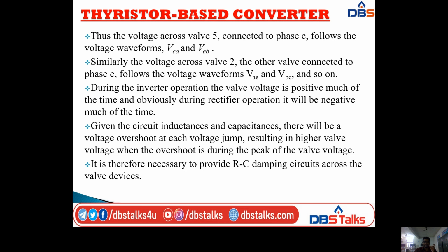Similarly, suppose you take the voltage across valve 2, the other valve connected to phase C. It follows the voltage waveforms VAC and VBC, and so on. Like that it will continue. During the inverter operation, the valve voltage is positive much of the time, and obviously during rectifier operation it will be negative much of the time.